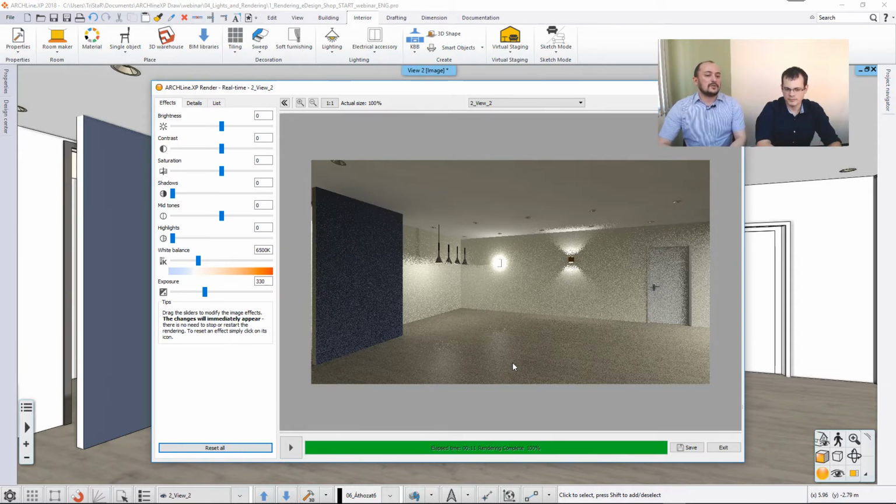And then also you should focus on things like this. If you don't have a powerful computer, then you can render with that, but you should be more aware of the number of light sources that you have. And light sources are coming in several forms. Like there is light source that I just designed. It's a simple light source. We call it a spherical or point light source, which is the simplest. It's easy to calculate for the renderer. But there are linear light sources, which I will design now. We'll look at them in a minute. Which is a little bit more difficult to calculate, but it's also more pretty in many situations.